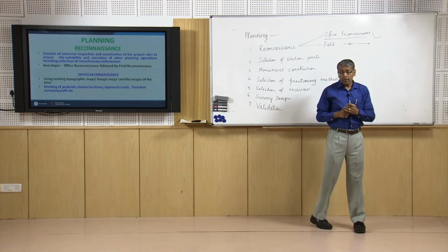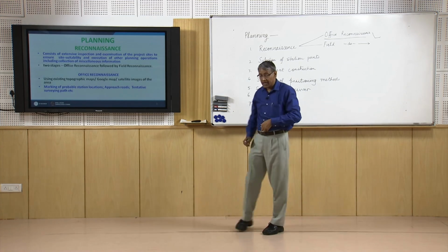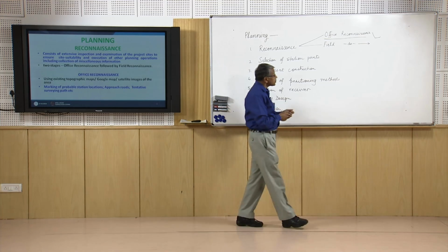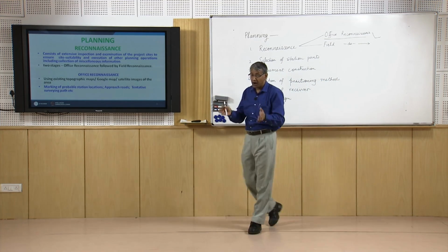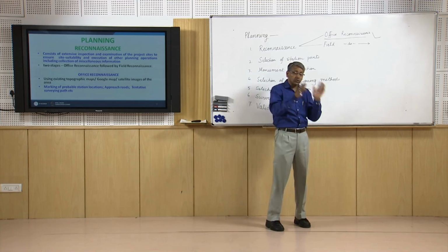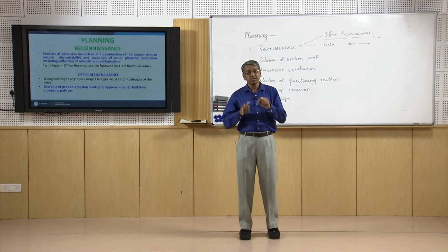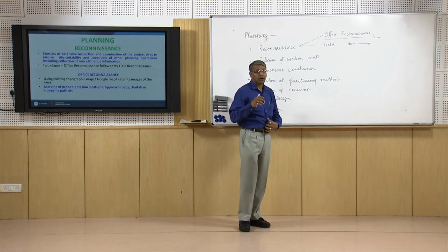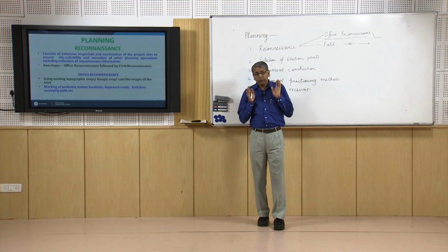Now, during field reconnaissance, the most important thing is to identify the actual location of the probable stations which have been marked in the base map, and then we should go to the field and find out whether those stations are really suitable for GPS surveying or not.